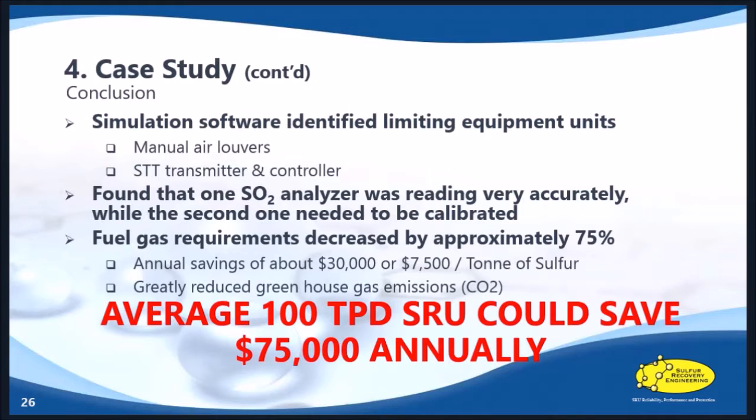So in other words, by reducing the stack top temperature to 325, the fuel gas requirement drops and the corresponding annual saving could be achieved. In addition, the saving is just in terms of fuel gas. If we add up the cost associated with the carbon tax, then the saving could increase even further.